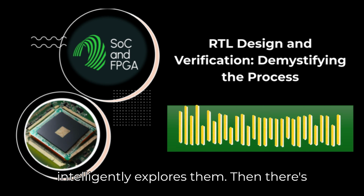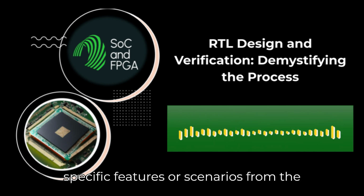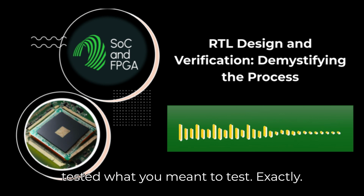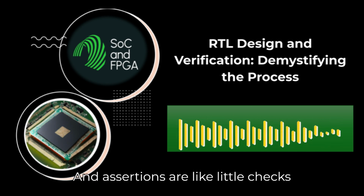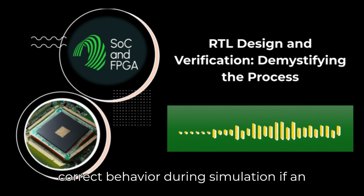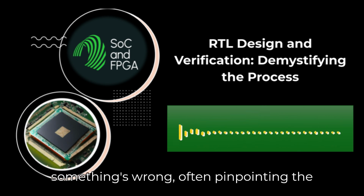Intelligently explores them. Then there's functional coverage. This isn't just about running code, it's about defining specific features or scenarios from the spec and measuring whether your tests actually exercise them. Making sure you tested what you meant to test. Exactly. And assertions are like little checks embedded directly in the design or test bench code that constantly monitor for correct behavior during simulation. If an assertion fails, you know immediately something's wrong, often pinpointing the issue.